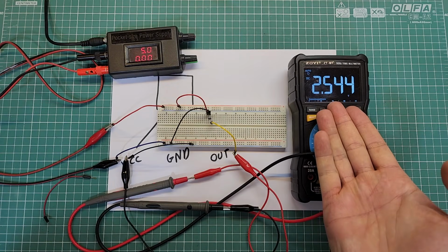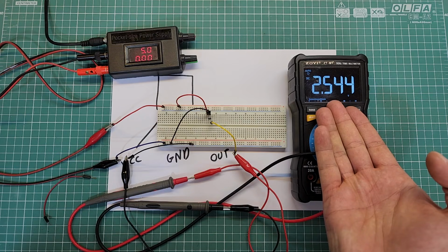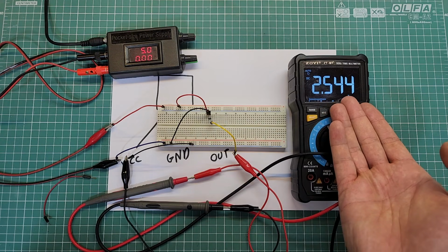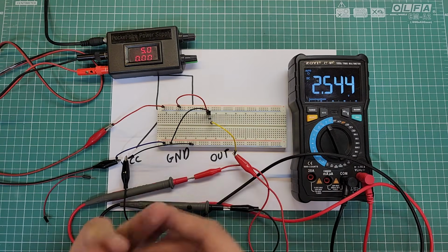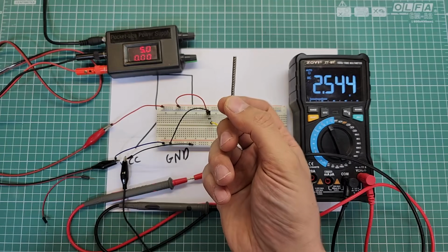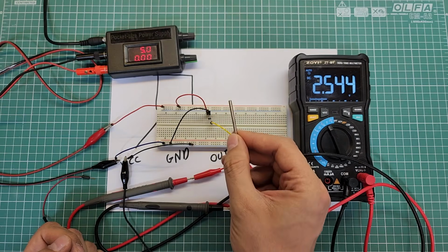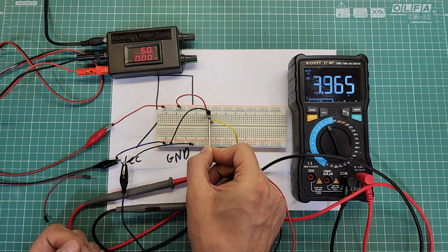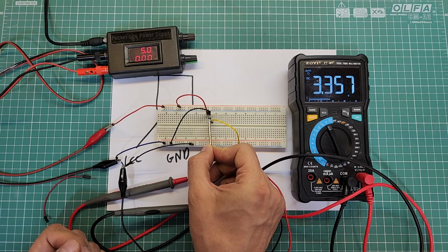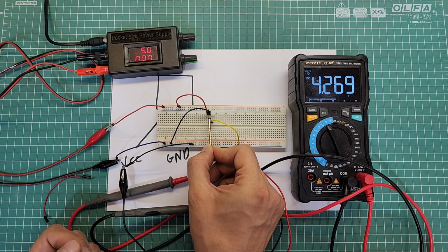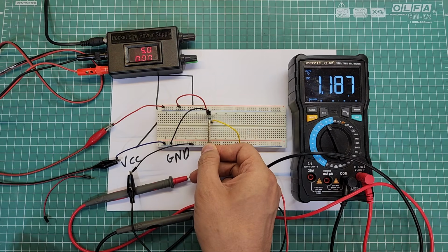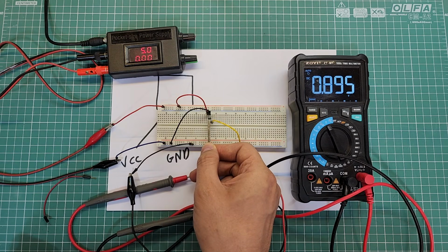Look at the voltmeter. In normal situation, the output voltage is something around 2.5 volts, which means that the magnetic field does not exist here. By putting a magnet near the sensor, the voltage at the output pin changes. One of the magnet poles will cause the output to approach the source voltage, and the other one will cause the output voltage to approach the ground voltage.